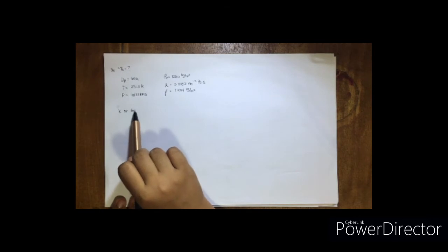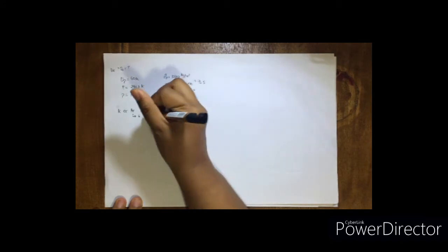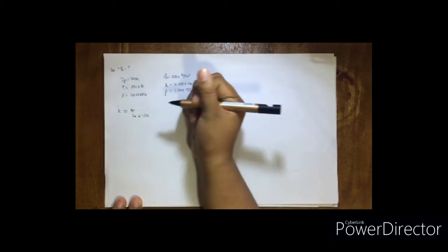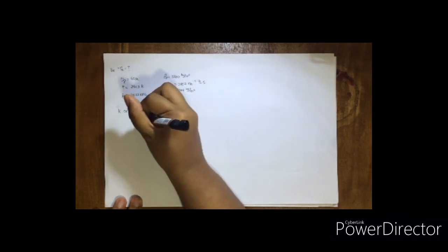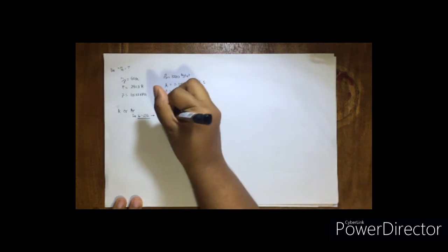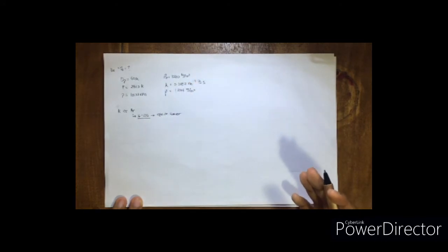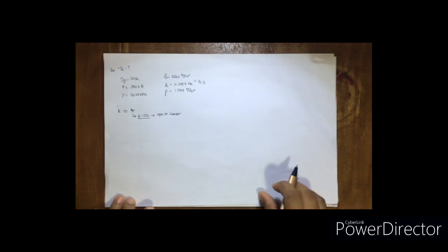The formula for the Archimedes number can also be found in your Perry. I think this is chapter 6, equation 6-236. This is the equation for the Archimedes number, so you can also use this to determine which formula for terminal settling velocity you will use.